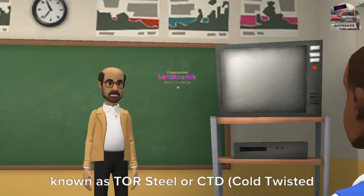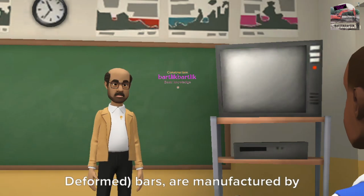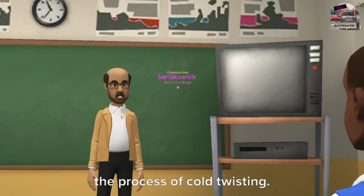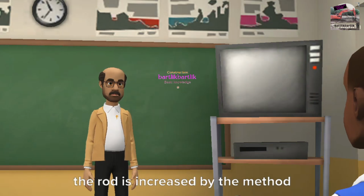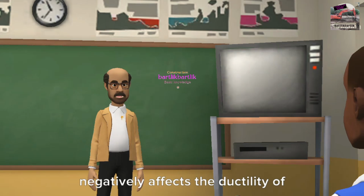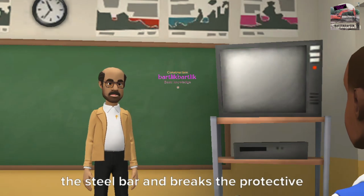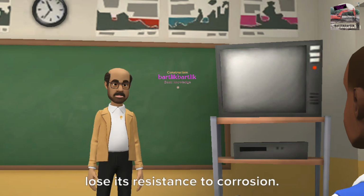Cold twisted bars. Cold twisted bars, also known as Torsteel or CTD, cold twisted deformed bars, are manufactured by the process of cold twisting. Generally, the tensile strength of the rod is increased by the method of twisting, but this method also negatively affects the ductility of the steel bar and breaks the protective blue oxide, which makes the CTD bar lose its resistance to corrosion.